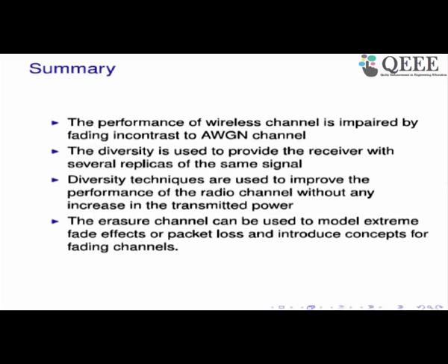I have introduced a space-time code from the perspective of trying to achieve full diversity. And I have shown you that you cannot have full degrees of freedom because the received symbol has only NR variables. So it cannot have the NT-NR number of degrees of freedom that is there in the channel. So you need to do something in time. You definitely have to have NT replicas. Then only you are going to get a diversity of order NT-NR. So that summarizes the complete discussion till now.